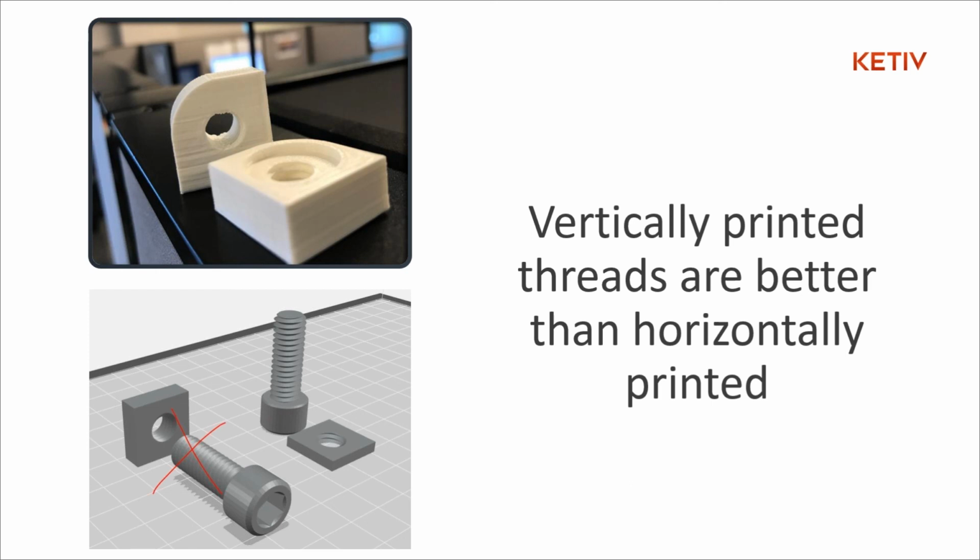The other thing too is to print bolts head down. Generally, you don't want the end of the thread pointing upwards, because then you would need support material on the bolt heads and stuff, and that is not fun either. So just use common sense. Yeah, essentially.